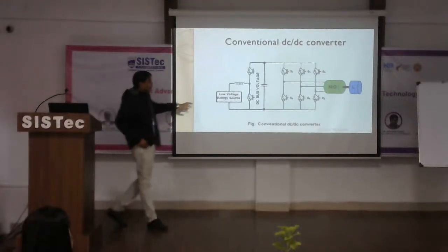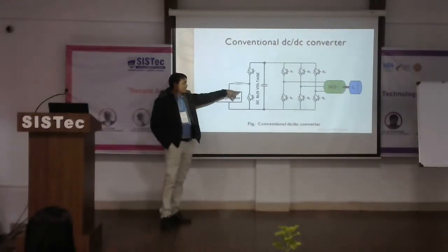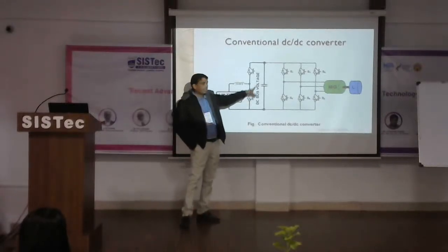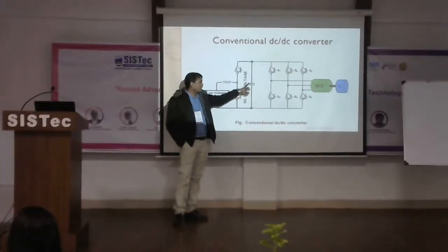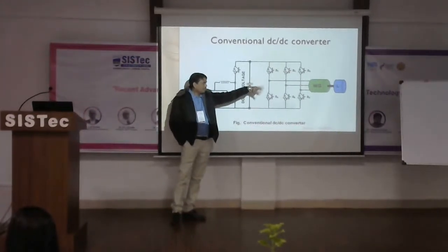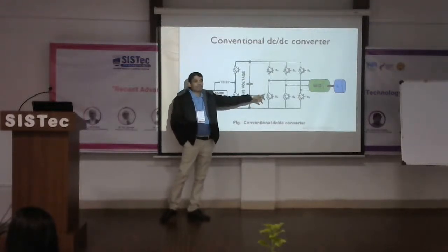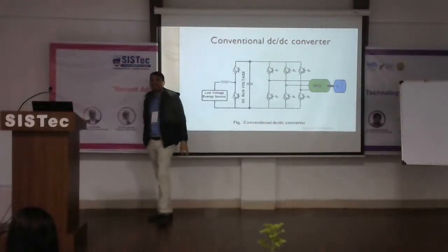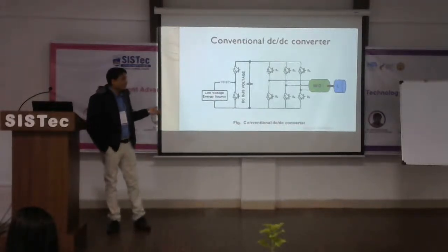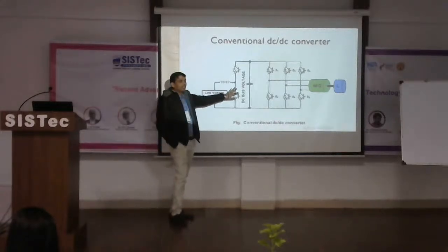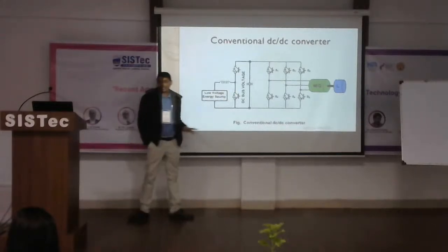In that case we step up the DC voltage by this DC-DC converter, and we get a variable voltage, not maintained constant. That variable voltage is again given to the input side of the motor generator side, and that is converted to AC. Okay, and the same phenomenon will be done. Only in that case, this DC-DC converter works as a bypass.